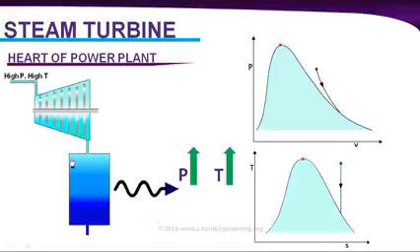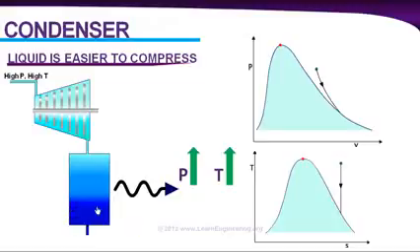Like this. You put a condenser over here that can reject heat to the surrounding. So vapor will get transferred into liquid state. Now this process can be drawn in PV and TS diagram like this. And during heat rejection there is no pressure change because fluid is free to expand. And obviously this is phase change, so temperature cannot change.